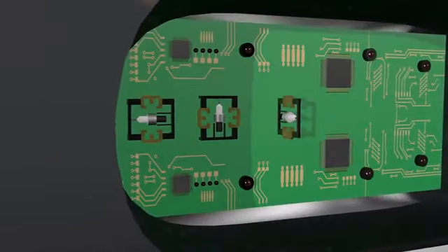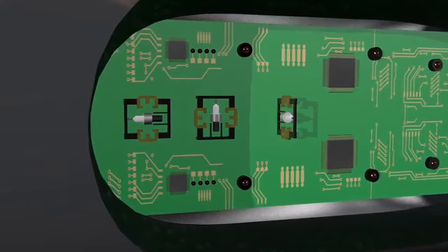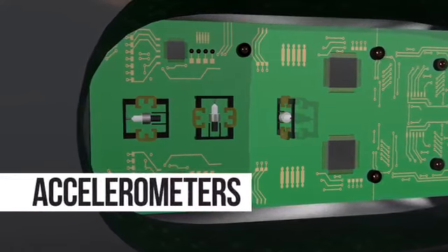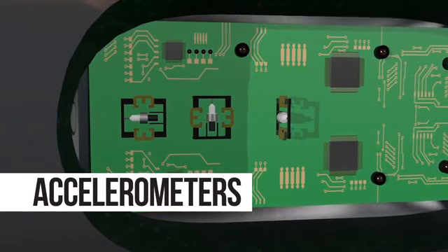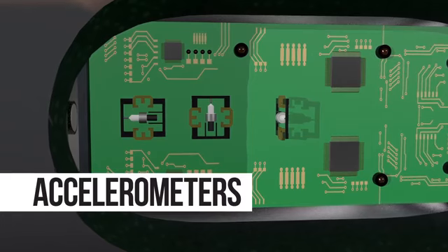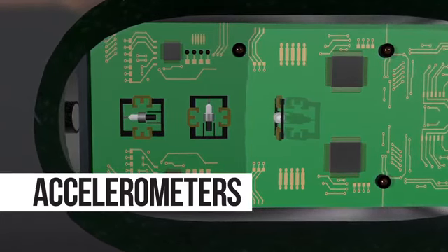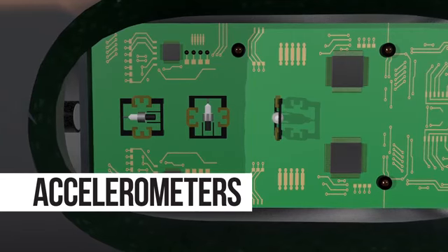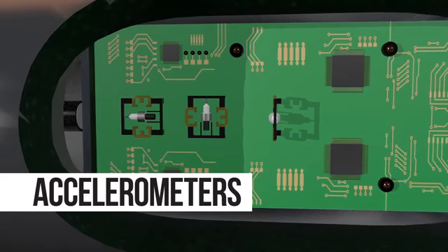In addition to the tool's magnetometers, there are also 3 similarly arranged accelerometer sensors. The accelerometers are used to measure the Earth's gravity field, informing us of our orientation relative to vertical or down. They also serve, importantly, as a reference for the magnetometers.